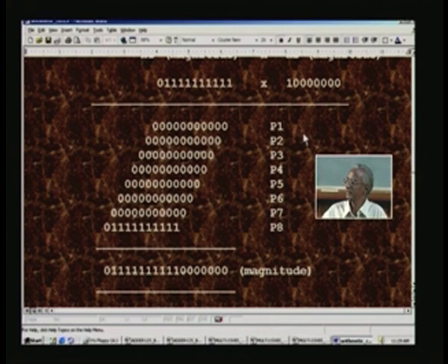Likewise, those 2 when added in the second stage will produce one more output, and similarly from this you will get one more output here. Notice that at the last stage there will be 2 inputs, and those 2 inputs are staggered by 4 bits, because it is the result of these 4 here and these 4 here. So when compared to the first one and this second group, you have 4 bits: 1, 2, 3, then 4. So the third stage will be 4 bits shifted, and that is how it is.